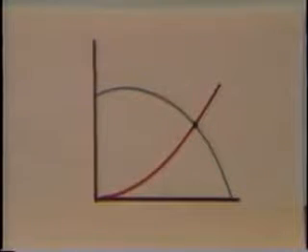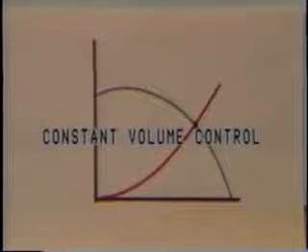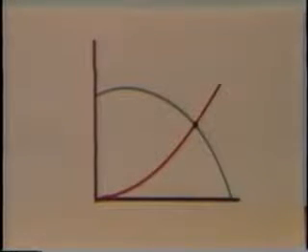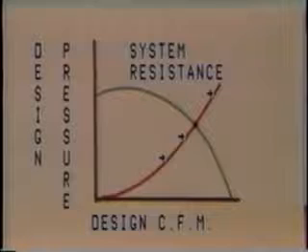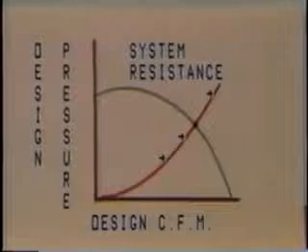Looking back, we have addressed sensing pressures and the basic types of VAV systems. Now, let's get more specific and address the methods of controlling fan discharge. The first method concerns constant volume control. With constant volume systems, the fan is initially set up to operate in accordance with the selected point of operation from the fan characteristics. Fan control of constant volume systems is, for the most part, non-existent. Peak loads are summed up during the time of system design, and the fan is selected and initially adjusted accordingly.